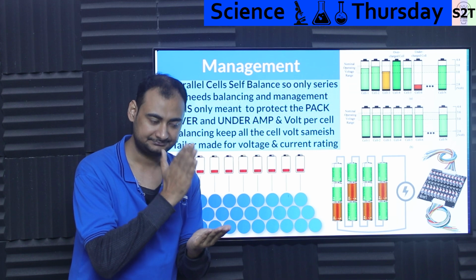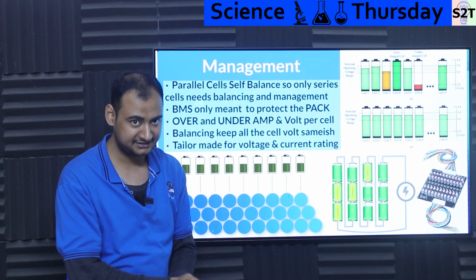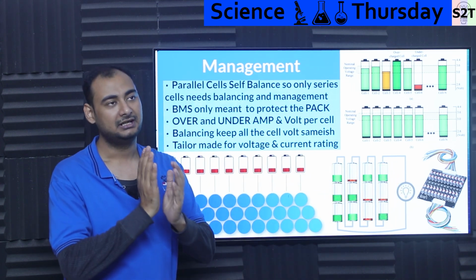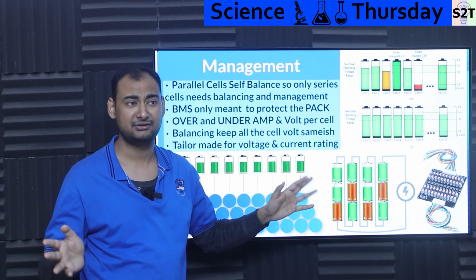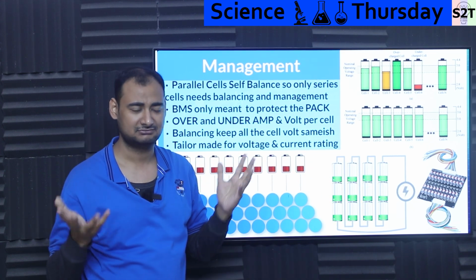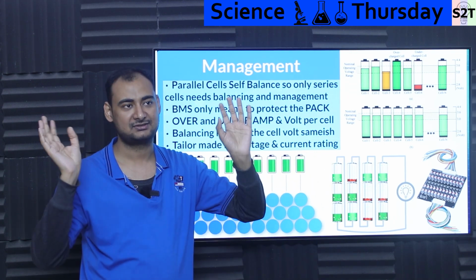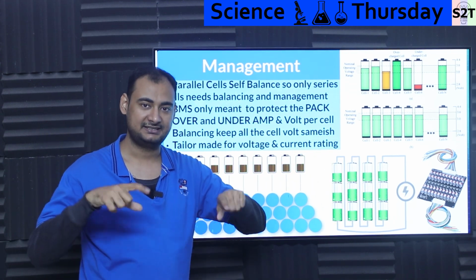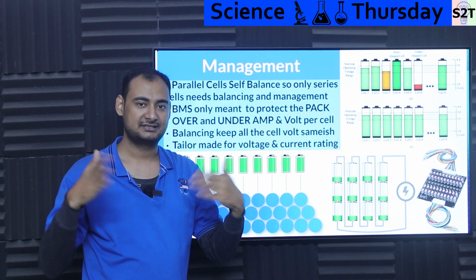So if you have very well matched cells, and then you have a very good balancing circuitry like this Blackmagic technology, I have made a detailed video. I do understand how a capacitive balancer works, but do not ask me how an inductive balancer works. I do not understand that voodoo magic. But the capacitor one, I understand. It just attaches all the capacitors in basically series to the cells, and then it parallelizes all of them. And it does it at very high frequency.